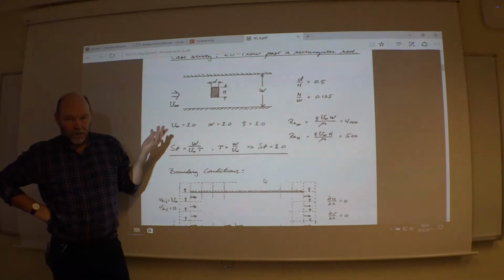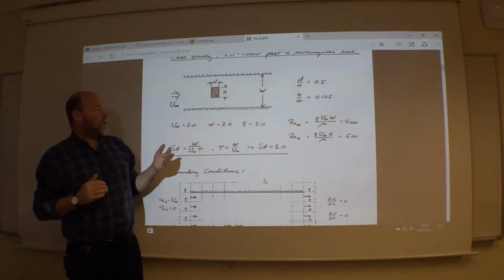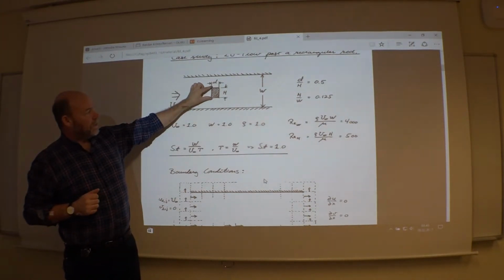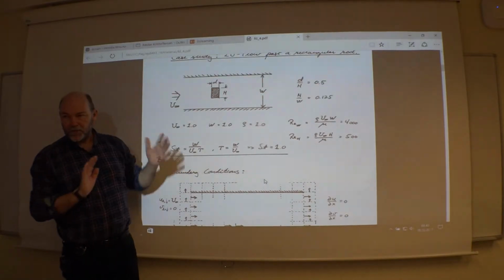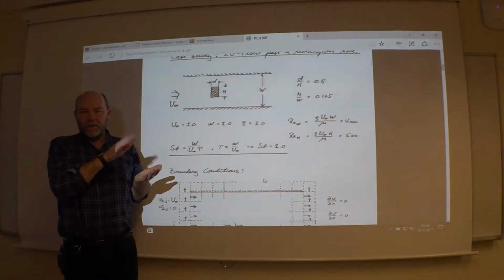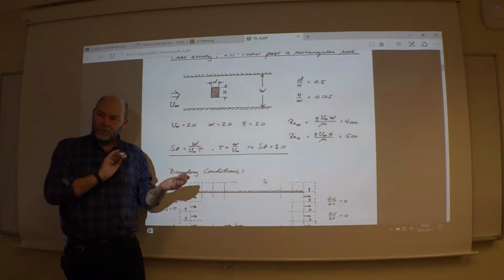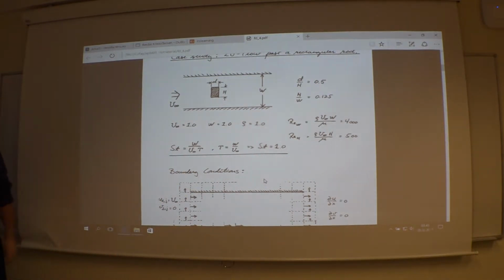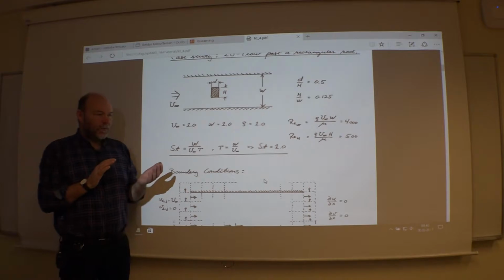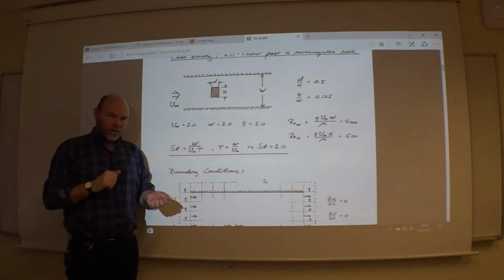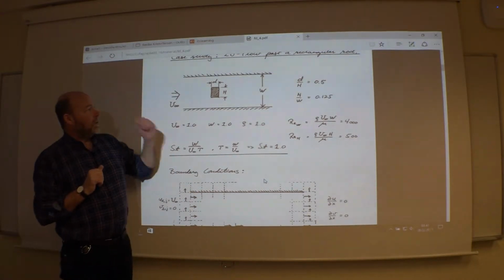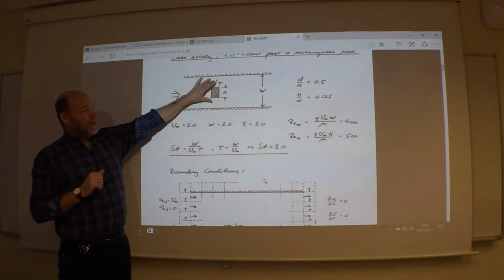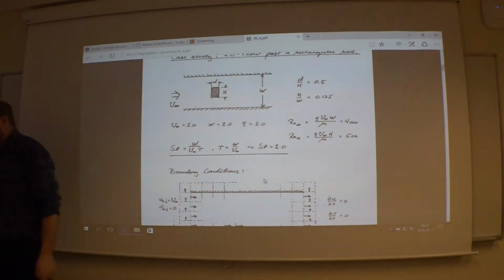It's just unstable. So it would actually be better if you have this one a little bit, maybe one cell down, so you have some asymmetric problem. Then he will start the shedding faster. Normally, if you run a long time, he will manage to get enough errors to sort of see that it's not symmetric anymore, and then start with the shedding. But to help him, you could make it a little bit asymmetric.